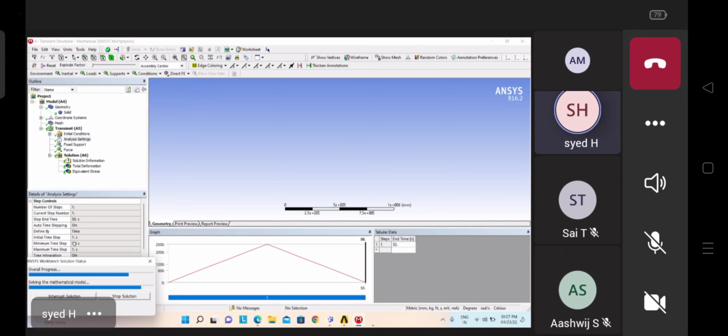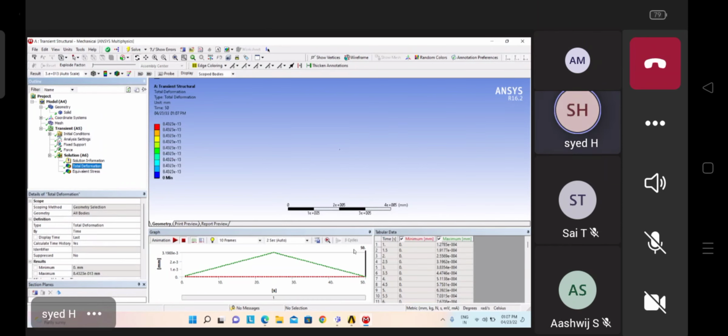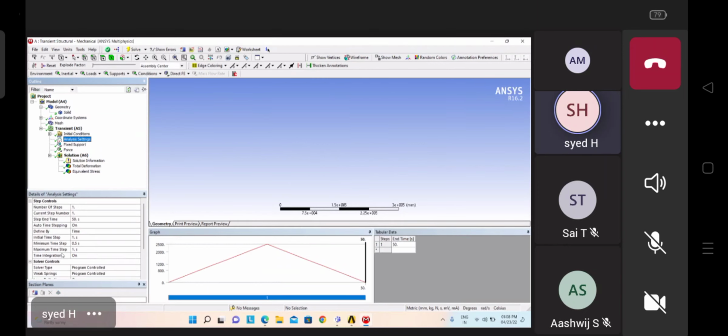For example, here, if you go to results and check now, you can find in each result a 0.5 second gap. For each result, here 1, 1.5, 2, 2.5. So these are the time interval steps which we are giving here. So for every half second, it is showing the result. That is the thing you are specifying in the analysis, that is 0.5 seconds.